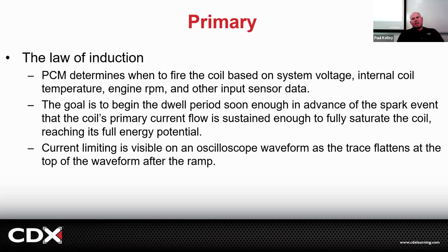So, in fact, somebody asked me on YouTube literally yesterday, one of the discussions you guys are going to do later is how to set ignition timing. When we go to set ignition timing, we're really setting the base ignition timing, and then the computer is going to take over and do the advancing and the retarding as needed. As needed based on all this, and especially sensor data.